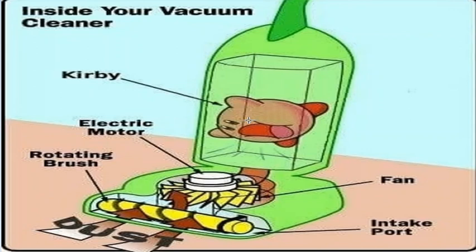Same principle will apply to the ESP also. ESP rotor will rotate from the energy from the motor. That rotation will create suction. It will suck oil, give energy to the fluid. That energy will be sufficient to lift our fluid from the bottom to the surface.